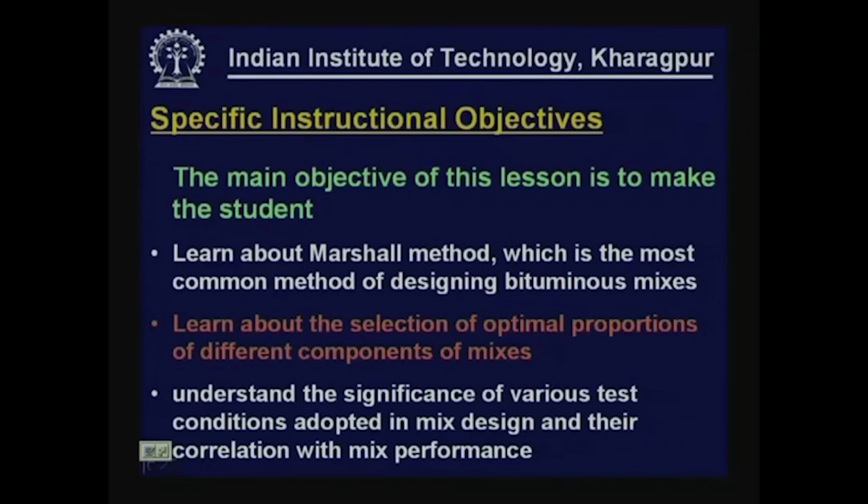In fact, in the previous lesson on bituminous mix designs part 1, we have covered various aspects such as what are the important parameters that are to be considered in designing mixes, what are the requirements of mix design, and we have also identified that air voids, which is a volumetric parameter of bituminous mix, is one of the most important parameters to be considered in designing the mixes.